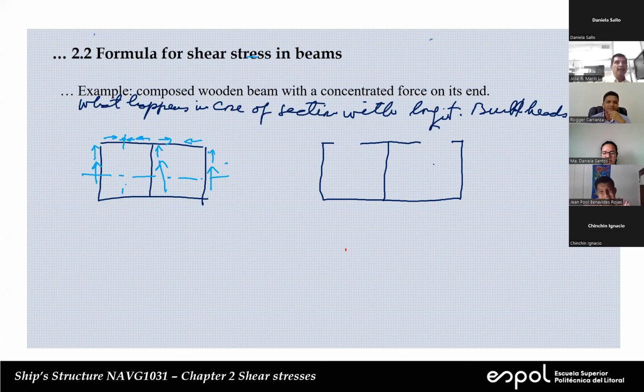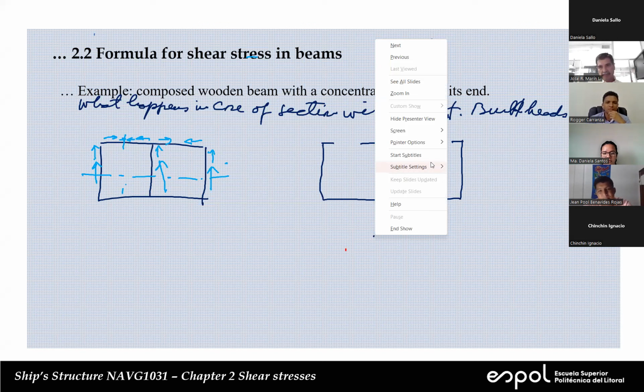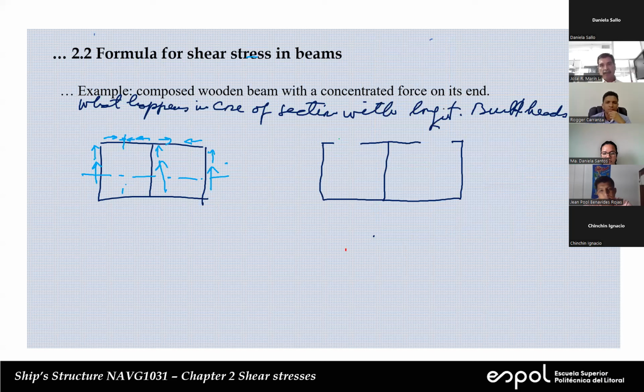Now, for example, we can make a cut. Let's do several cuts. So let's do a cut here. Okay, so let's include probably about here. We're going to have a neutral axis there. Yeah, we can calculate because the y is going to be constant. The area will vary linearly, so we have a linear variation. Fine, we can do it.